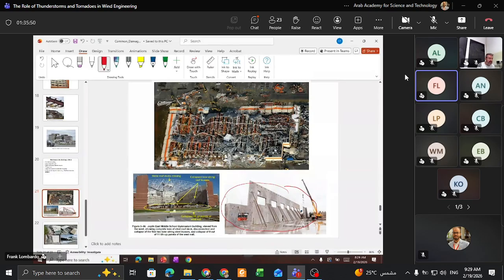Before the roof goes in and they get connected together, they're tilted up and these temporary braces are put in to hold the walls up until the roof gets connected. So that could give you an idea of the stability of those walls if there's nothing holding them together.